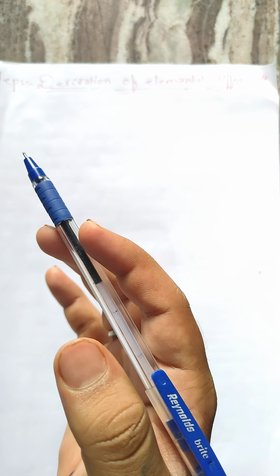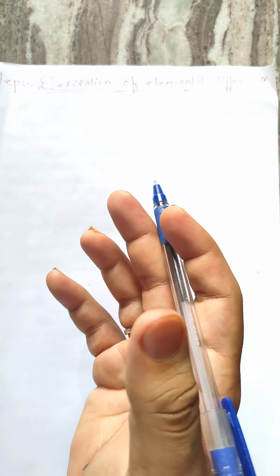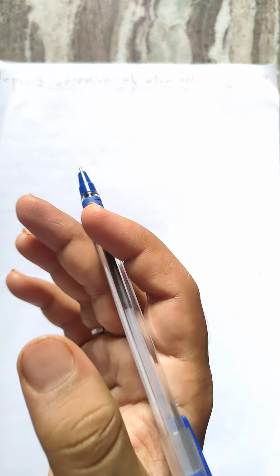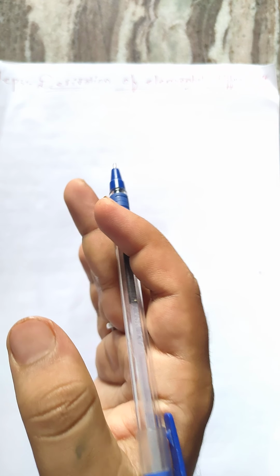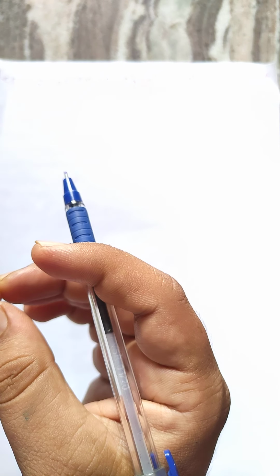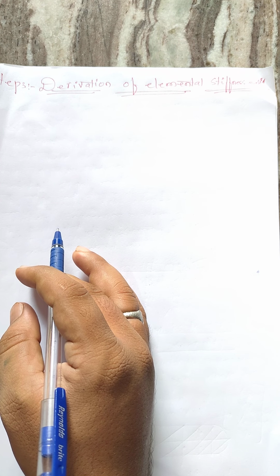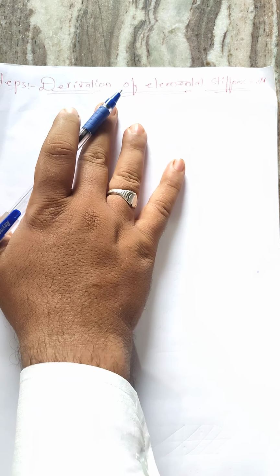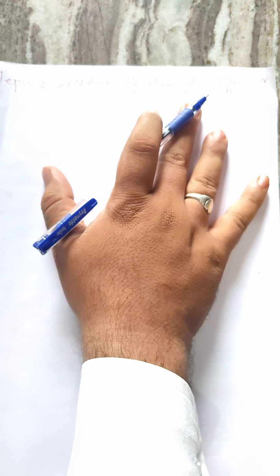So we know very well that the equilibrium equation for any element is determined by using the principle of minimum potential energy. The equation is stated as Ku equal to F. The K indicates that it is an element stiffness matrix, U represents the nodal displacement, and F represents the nodal force matrix. So this method we need to adopt in the problem. Is it right?